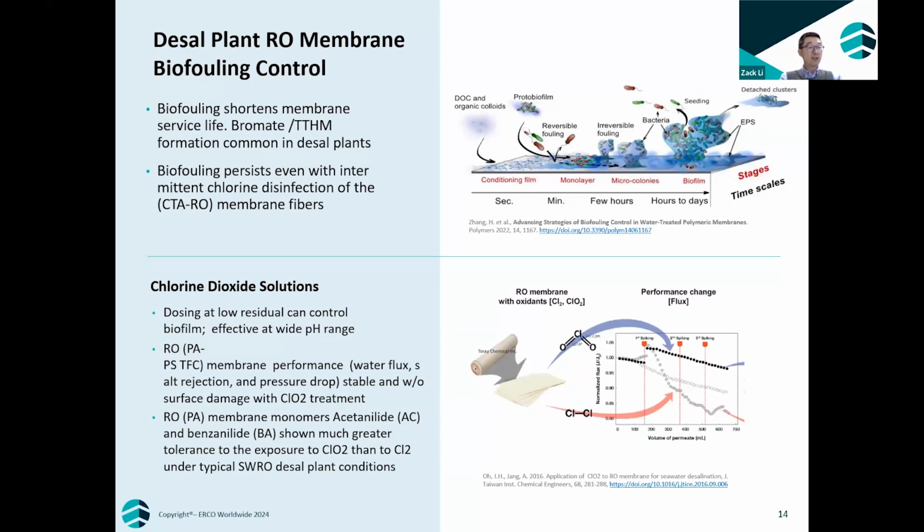Seawater, however, has a natural content of bromide, usually around 65 to 80 ppm. Chlorine oxidizes bromide to bromine, so essentially chlorination becomes a bromination process, which forms bromate and bromoform DBPs. Both are very tightly regulated DBPs by US EPA.